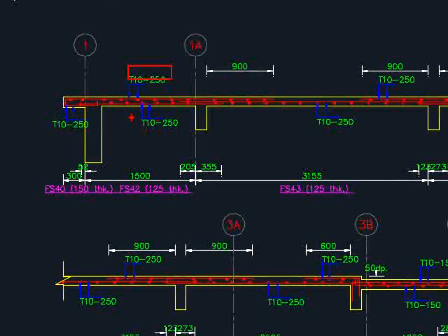Properly label the reinforcement bar in terms of the size and the spacing, which in this case we standardize to be T10-250. Make sure whichever you give must be adequate to resist the loads acting onto the slabs. As the slab size is not really large, the provided reinforcement bar is more than enough.